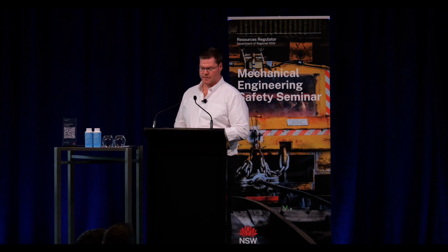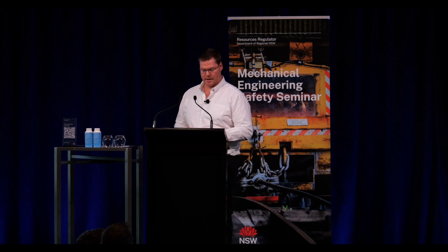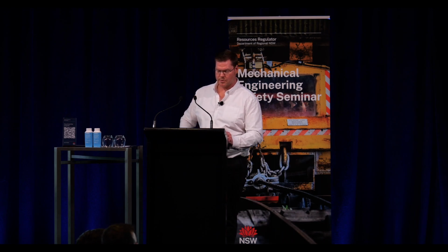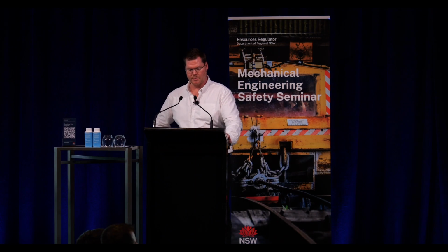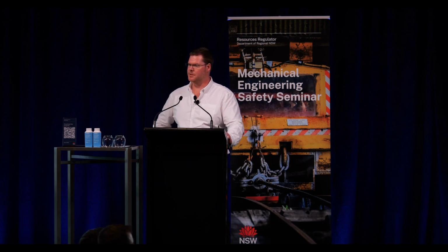Tension meters, they're similar to inline load cells, however they're clamped to the side of the rope where you bend it, and you can measure how much tension and rigidity is in that rope. Load indicators, you often get them attached to the rope end or the rigging itself. So the use of line pull monitoring can be used to limit and ensure the equipment is appropriately sized for the task. So limiting the torque output or energy consumption by the equipment and making use of continuous monitoring that trips the equipment in the event maximum limits are reached.